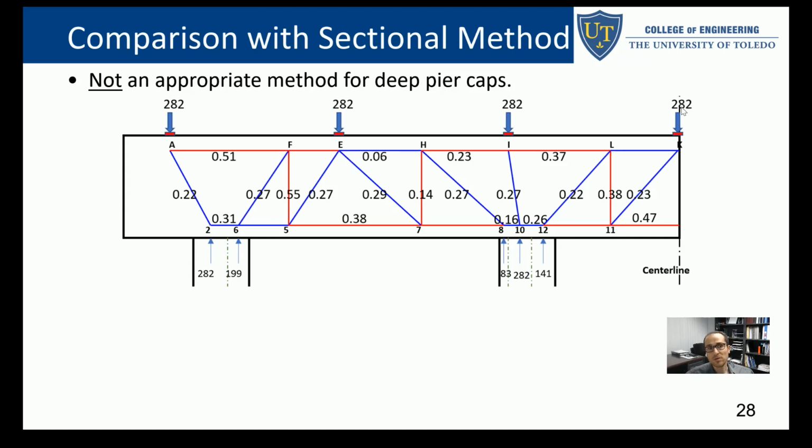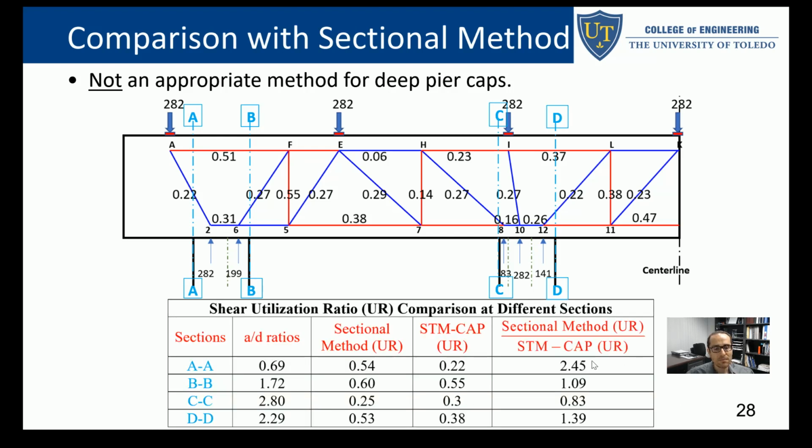Sectional method shouldn't be used here, but just for the sake of demonstration, we used it. And in almost all cases, the capacities are 2 times larger, or the utilization ratio is 2.45. So it's going to be overly conservative for deep members.